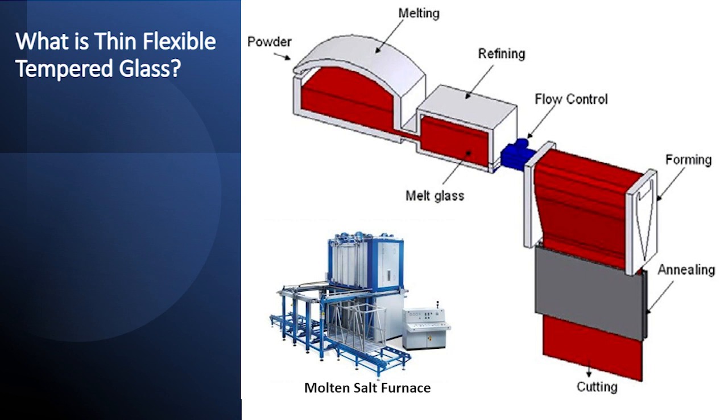Unlike the process for manufacturing float glass, the fusion flow process ensures that no machinery contacts the glass until it is sufficiently solidified. By having the molten glass overflow from two flat sides of the glass former before rejoining into a single stream, fusion flow results in a smooth and clear glass sheet.